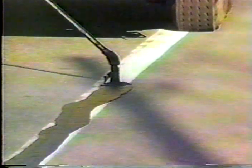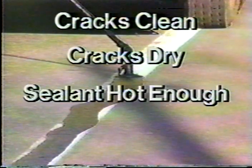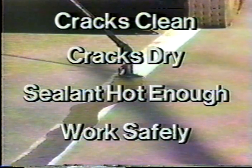We have just been through the steps necessary to achieve a successful crack sealing operation. The important things to remember are: cracks must be clean and dry, the proper material must be used at the correct temperature, necessary safety precautions must be taken.